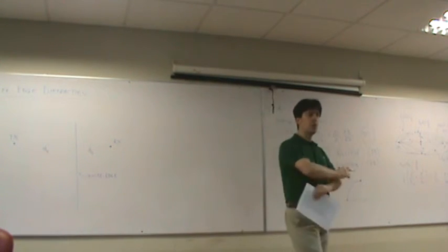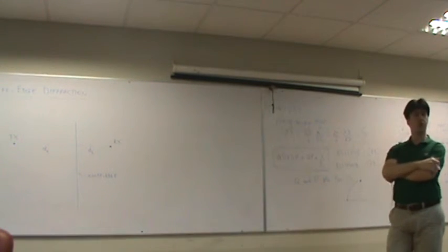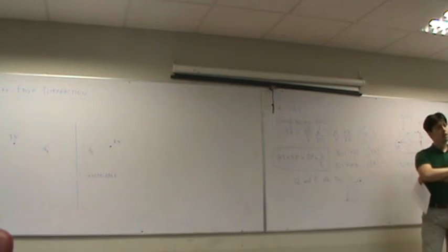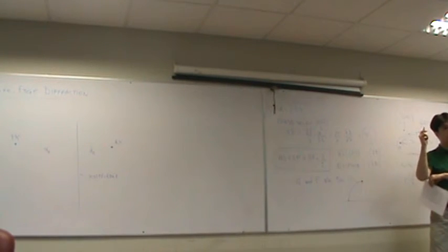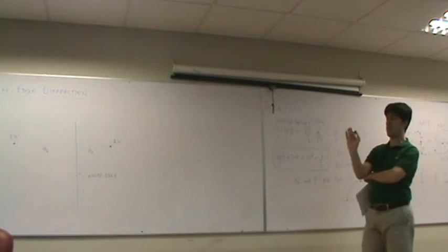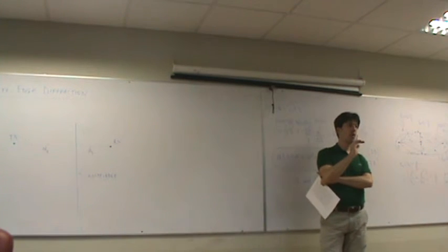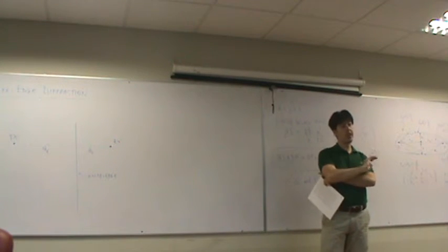So let's call D1 and D2 the distances from the transmitter. It's actually irrelevant which is transmitting and which is receiving, because you have to keep in mind that the radio channel is reciprocal. That is, insertion losses going from point A to point B are always the same as going from point B to point A. So it is irrelevant who is transmitting and who is receiving. The channel is always reciprocal. You go from one way to another and go back, losses are the same.